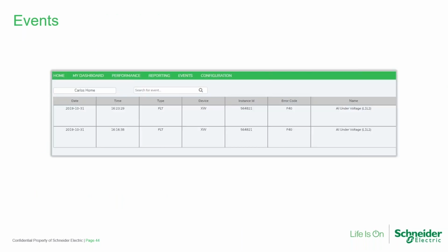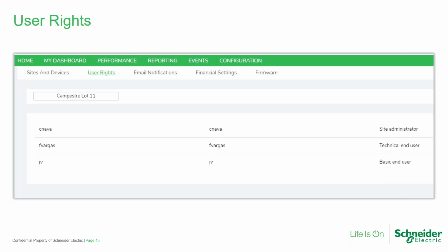Then we can look at events. We have a couple of choices with events here. This particular site has had 2 anti-islanding events. Here I'm told what date, what time, which event code and a description. It tells me what happened. In this case, again, anti-islanding fault. So these are issues with the grid. But I can also have different. Oh, I'm sorry. I'm jumping a slide here. Apologize.